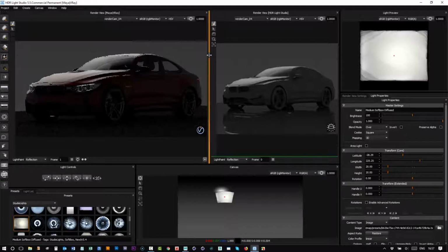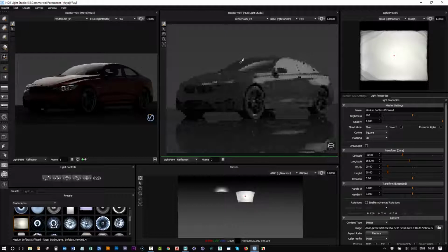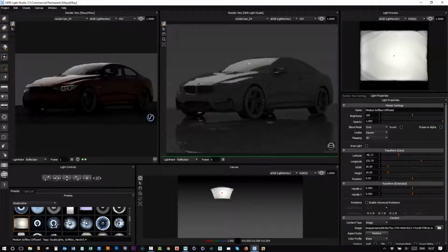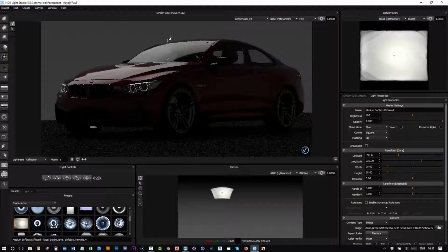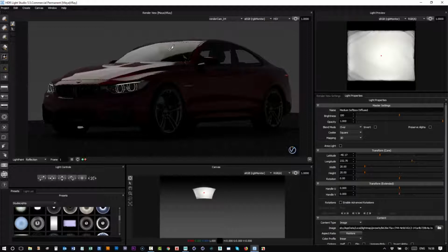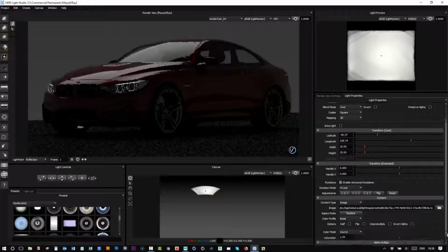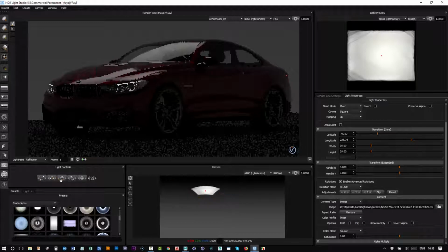So actually, unless you want that very interactive feedback to find the sweet spots on the lighting, you could not use HDR LightStudio's render view at all now. So if I just close that view, I can light this shot exclusively by using the V-Ray view. So for example, this overhead softbox, if I make that horizontal, it'll look better. And then I'll scale that up a bit.